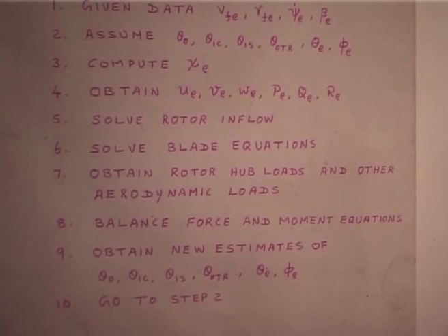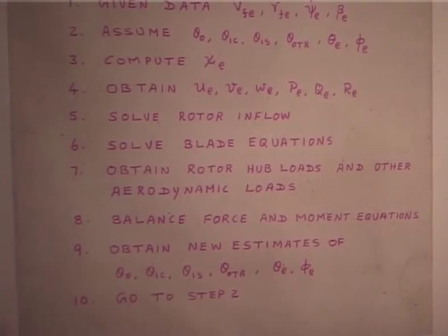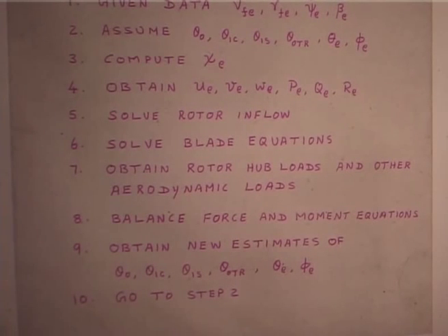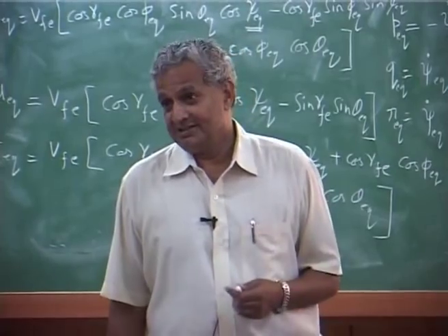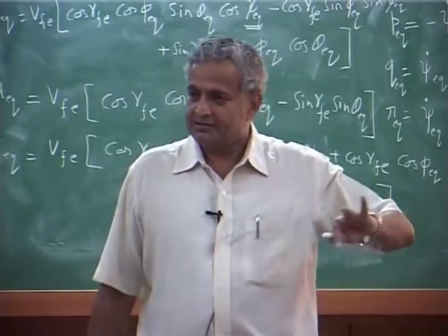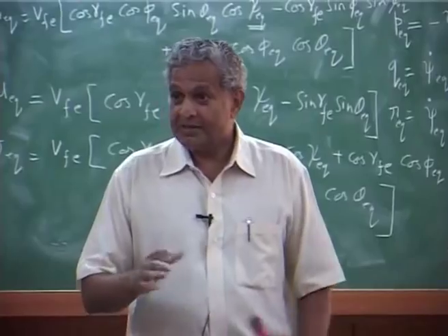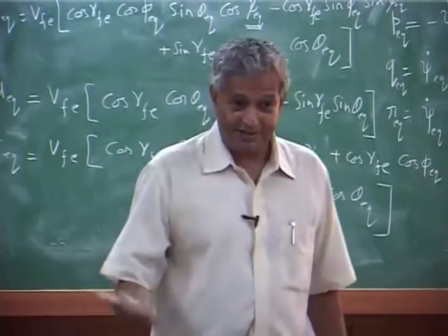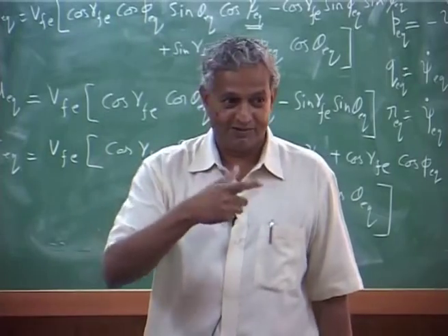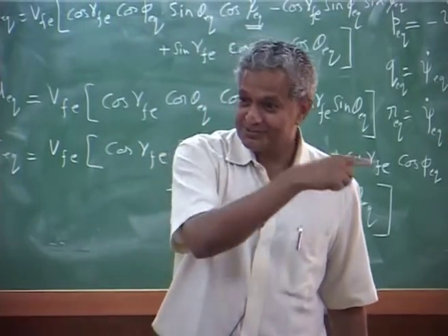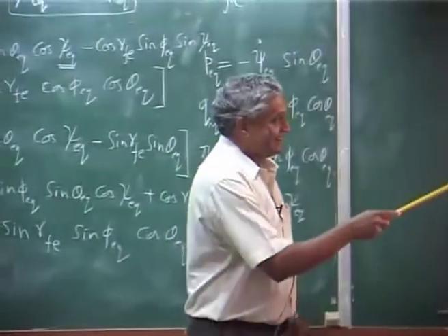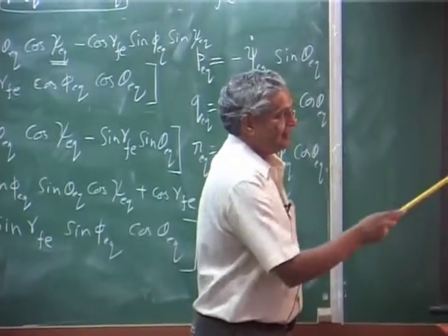So, usually these problems first you try to solve in a simplified way, take only flap, check whether the program is converging, because you will be able to get the mistakes from there. Once it is done, then you can say, okay, these are my loads, and if you want to include a stall model, please understand, when I get the aerodynamic load, I should have a stall model for the blade. I cannot have a closed form expression, everything has to be integrated in this part.